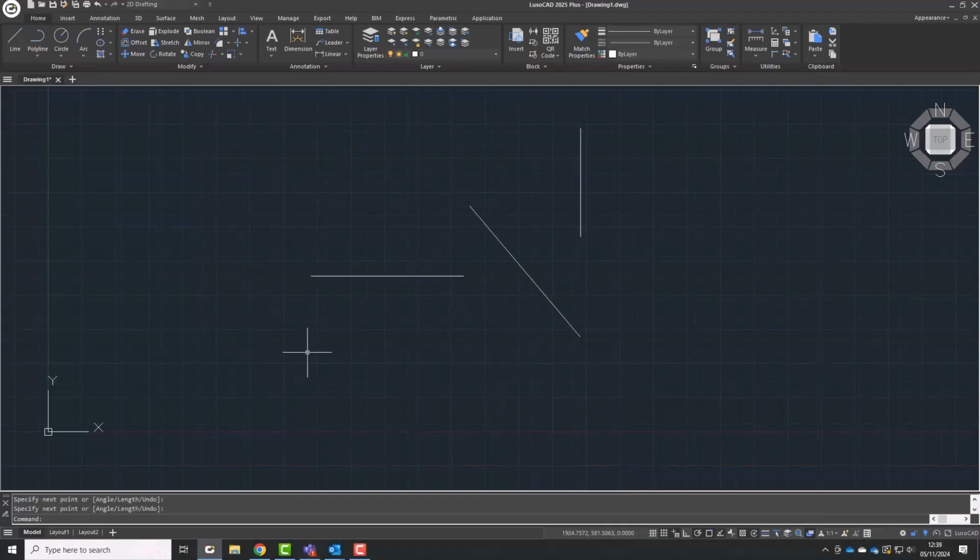Parallel will let us draw parallel to a reference line. It's good to know that ortho mode might make this snap object hard to use. First, when we start the line, hover over the reference line until the snap appears. Then, keep changing the angle until the snap reappears and lets us know that we are exactly parallel.